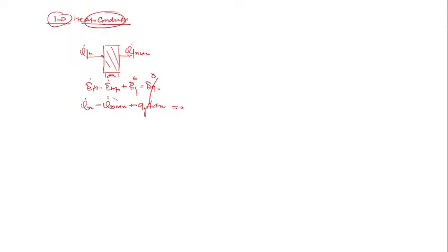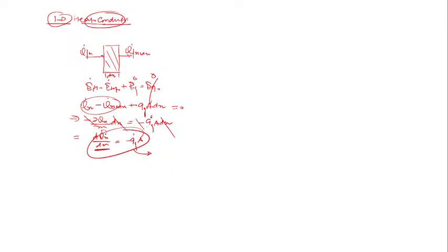And the difference of this is equal to minus del qx upon del x into dx is equal to minus qg into a into dx. This dx cancels out, and from Fourier's law the minus cancels out, and del upon del x becomes d upon dx because it's only a function of x here. And in this case, very interesting thing is that dqx over dx is equal to minus qg dot into a. It means whenever heat generation is there, the rate of heat transfer is a function of x. Yes or no? With respect to change in x, the rate of heat transfer will vary.